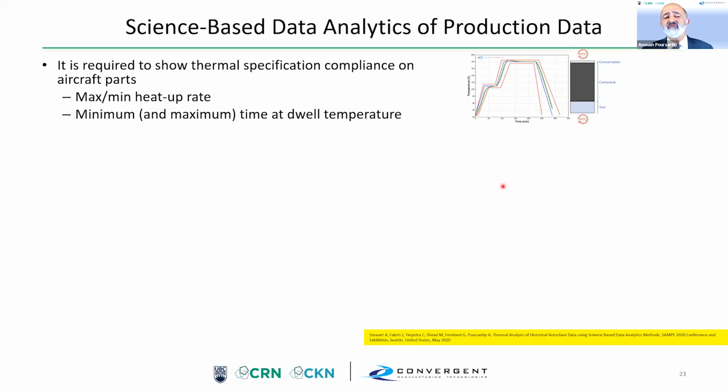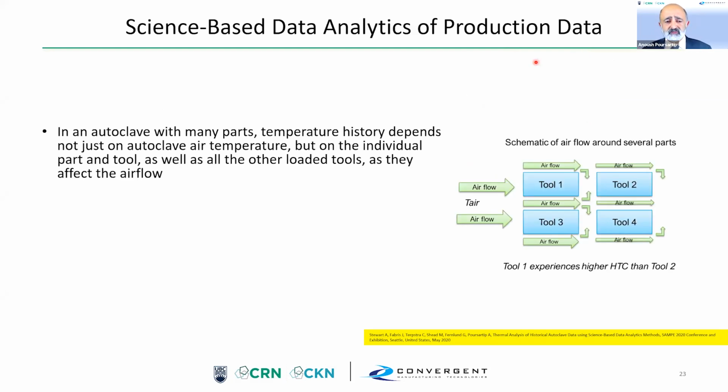So again, every part has to show that it has met the heat up requirements and it has met the requirements for how long it spends in the hold so that it's actually sufficiently cured. Interestingly, often you also are not allowed to stay on the hold too long because you can actually start degrading some consumables. The problem is that most autoclaves run mixed loads.